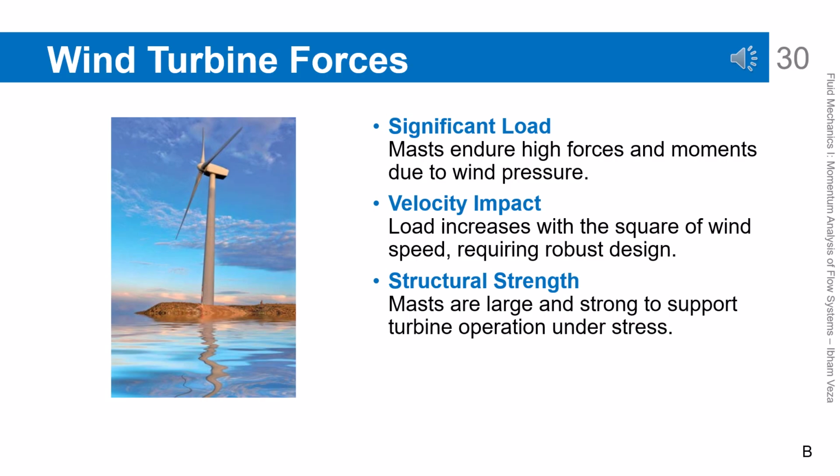Wind turbine forces. Wind turbine towers must withstand very large forces and moments due to wind pressure. The aerodynamic load increases with the square of wind speed, so the structural design must be very strong. In addition to horizontal forces, bending moments on the tower are also critical. Momentum analysis helps estimate the loads transferred from the airflow to the structure. Therefore, wind turbine design strongly depends on flow force analysis.